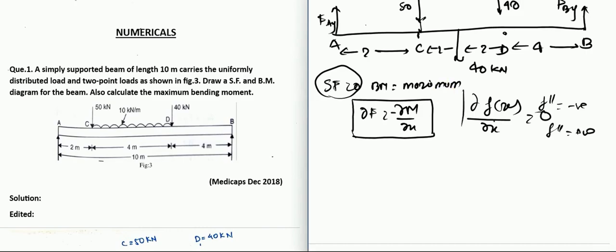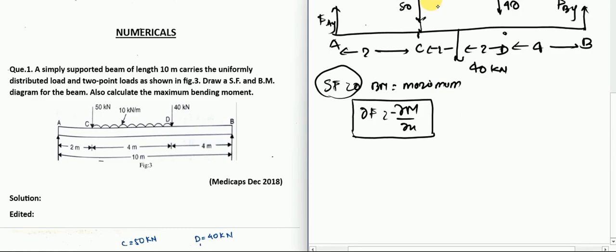We are using that same concept here. Whenever our shear force is 0, which means dM/dx is 0, the bending moment is at an extreme. If you want M to be maximum, dM/dx, which is the shear force, should be equal to 0. It doesn't matter whether the double differential is negative or positive at that point.